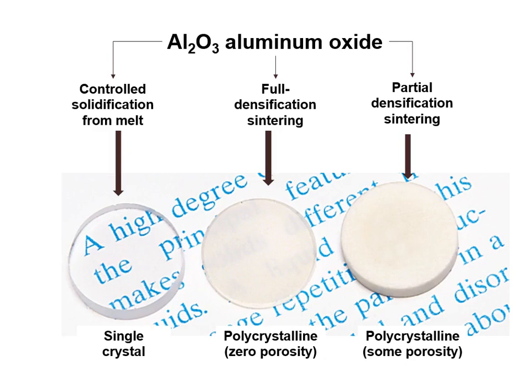Well, the first part of that process, the partial densification, leaves you with a structure that's effectively continuous aluminum oxide. It's solid, it has some reasonable mechanical properties for a ceramic, but it has a high void fraction, so it's effectively a composite of aluminum oxide and air.